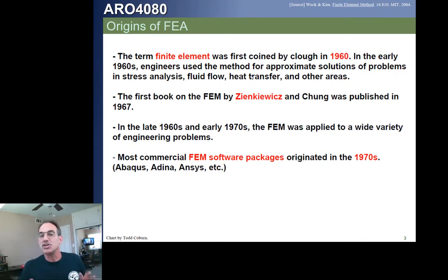Basically what we're going to do is break our structure into a series of elements. There's a considerable amount of judgment in figuring out what structural elements we can idealize. You can take an aircraft and idealize it with just a few elements if you want a very coarse model, just to understand how the thing flies through the air. In fact, you can idealize it as just a point, like a dot, as we did back in dynamics, before analyzing it as a rigid body. We can then go to a more complicated model where we idealize our stringers and our frames and different pieces, and we can get more and more fine models which become larger and larger mathematical problems.